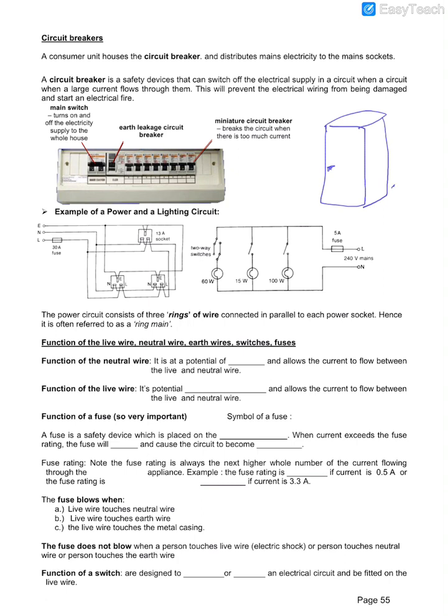If some fault develops in the fridge or the aircon, it suddenly causes a large surge, then it will cause one of these switches to trip, and your whole house has no more electricity. If it wasn't for this, your fridge would draw a very large current unknown to you. When we are all sleeping, it draws a large current, and then after that, a fire comes out. So circuit breakers are very essential, right?